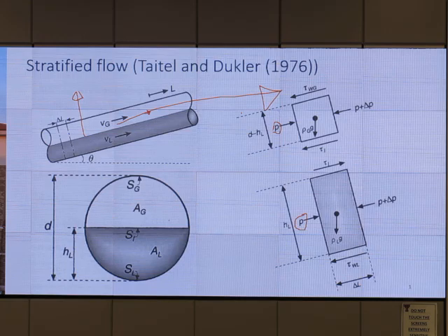June, what about time average velocity? Let's say we have single phase flow in the pipe, just gas. On average, do we have velocity in the radial direction? Time average means we measure velocity at 1 second, 2 seconds, 3 seconds, 5 seconds, measure several times, add them together, average. On average, do we have velocity in the y direction or just the x direction?